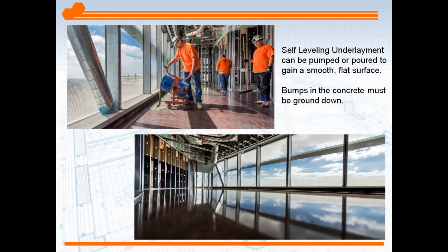The other way, and what's become really common nowadays, in fact, used to be specialized contractors did this, and they still do, of course, but tile installers are now getting into this in smaller projects and actually medium-sized projects. It's self-leveling. So a self-leveling product could be mixed and poured onto a substrate, and you'll see the gentleman on the left here in the orange shirt is pouring. This is called barrel mixing. So he's mixing that on site by the bag and then dumping it out. The gentleman on the right, he's going to make sure that product moves as it should to self-level, and it'll do exactly that. It'll self-level, find its height.